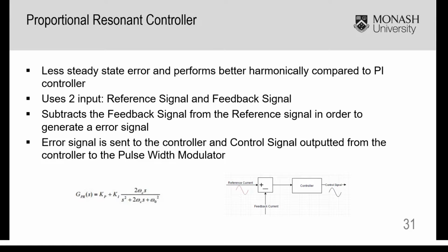We have decided to use the proportional resonant controller. This has less steady state error and performs better harmonically when compared to a PI controller. This controller uses two inputs, reference input and a feedback input.